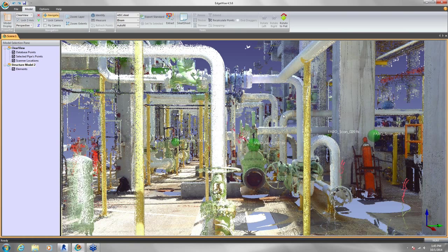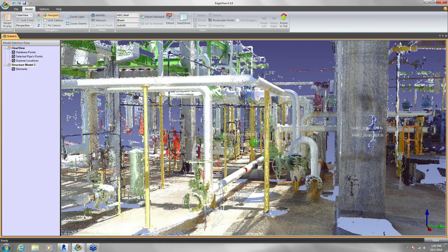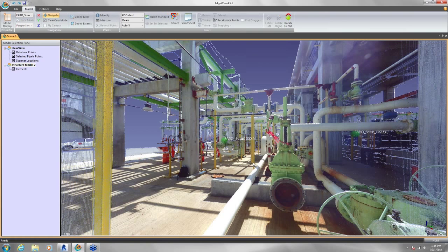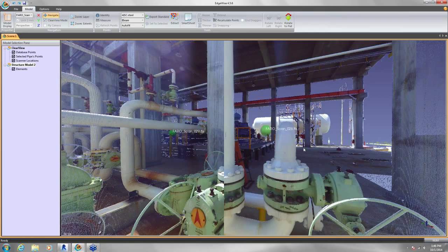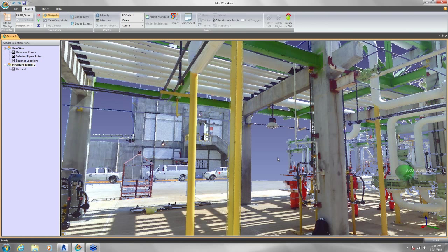Okay. So here we are looking at a full 3D point cloud of the guts of some chemical processing plant, and this is our standard visualization engine. But we've improved the ability to look from the point of view of a scanner. If I double click on one of these spheres, it's going to zoom me into that sphere and refresh the view, and it now looks like a photograph. But I'm still actually looking at the points. You can see a little bit of lag. We're actually still looking at the points, but it's cleaned up a lot since the last version of the software. I can zoom in, and it continues to just look like I've zoomed into a picture. So it now gives me a much clearer view that I can work with.